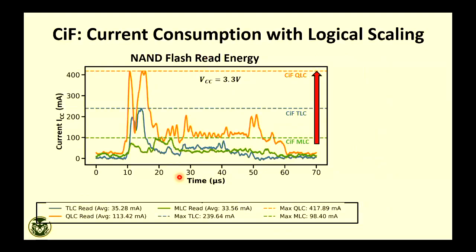Now, we can also quantify the energy efficiency of all these operations. Energy efficiency you can quantify if you measure current, right? Your supply voltage is fixed, 3.3 volt, for example, on a chip. But you can measure during your operation, when read is happening, what is the current consumption.